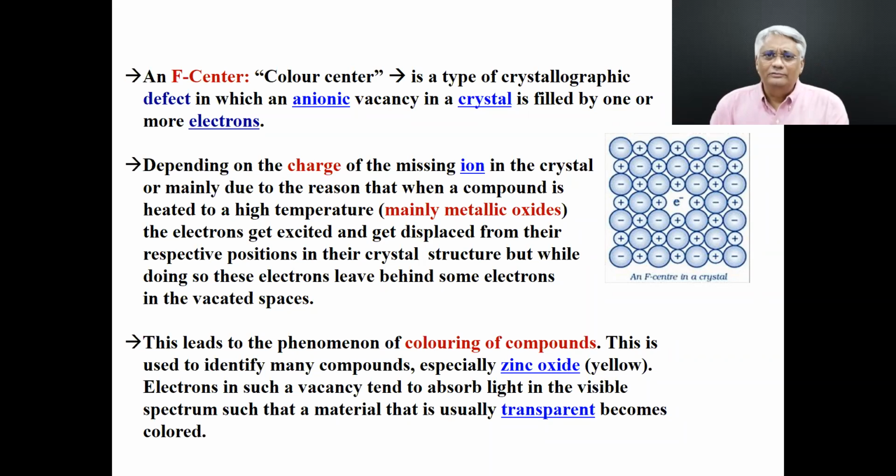Now they have plenty of applications, especially in thin film form. Most of these display devices, touchscreen devices, use these wide band gap transparent conducting oxides, because for certain applications, you need a top electrode which is transparent and also conducting.